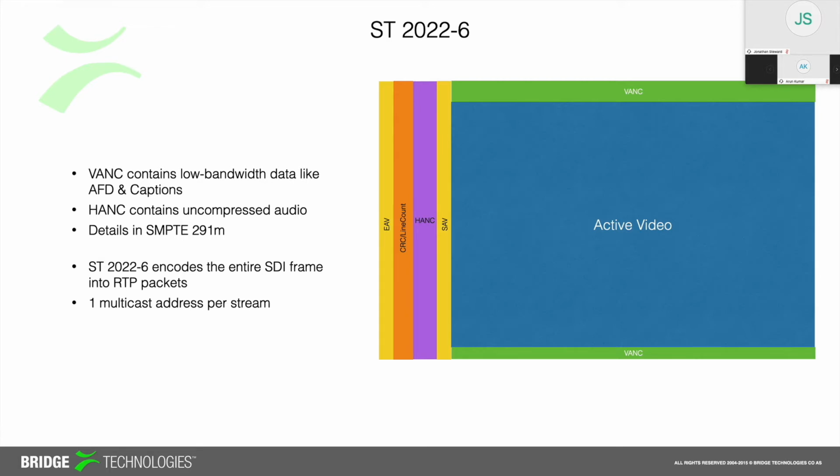There are some issues, well, not issues exactly, but vertical blanking causes an issue that we will see in a minute on another slide when we're talking about the type of receivers and senders. Basically, one multicast address carries the entire signal: video, audio, ancillary data and timing information.